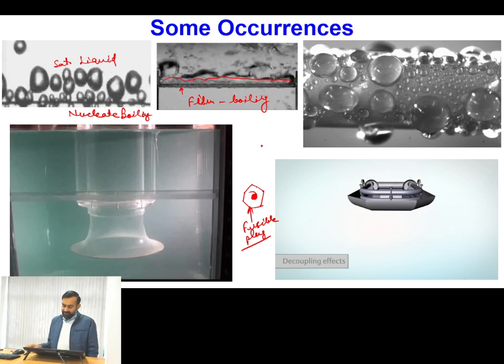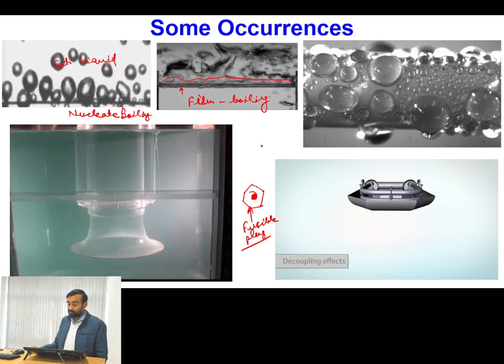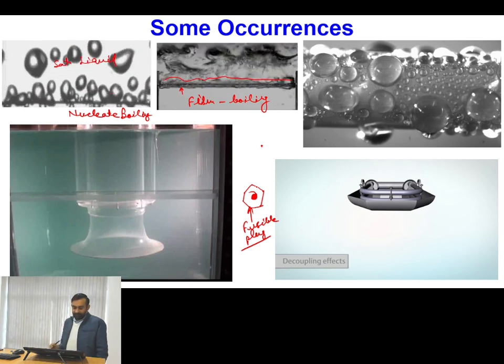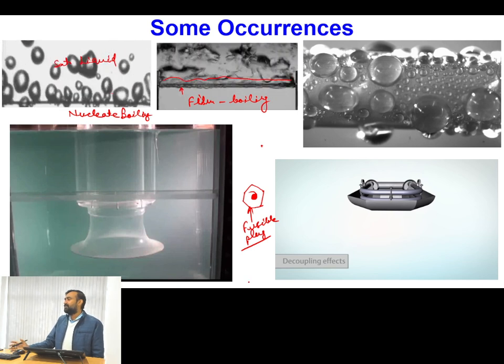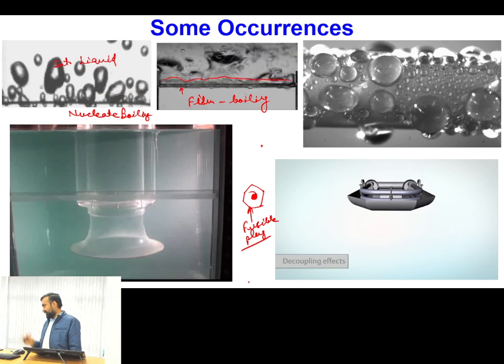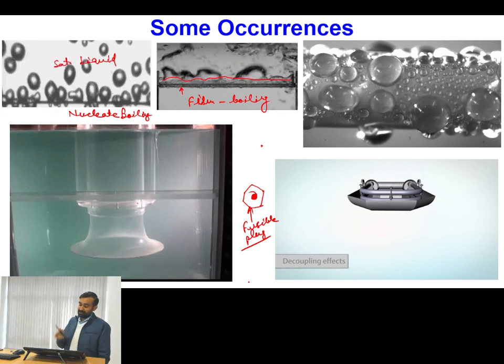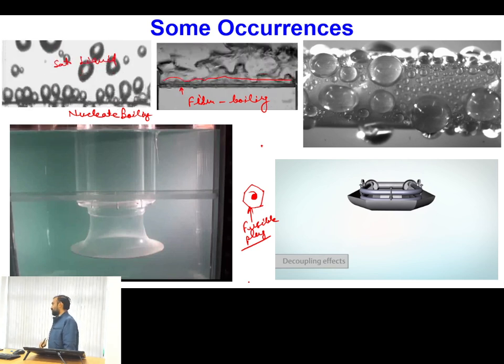So this type of system is even used in our boilers also. Okay, because a pressure cooker has steam in very small quantity, when you have a big boiler, the steam will be in large capacity. So there not only a single fusible plug is used, but some other safety installations are also done.